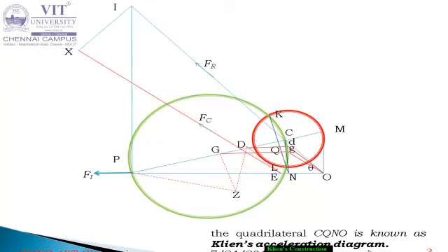Okay, so one component is over. Normal component we have taken, inertia force of the connecting rod we have taken, we have drawn the perpendicular distance Ix. For the normal force we have drawn one vertical line, but we don't know the perpendicular distance with respect to the center point. I and Fn are both acting in the same line, so there is no perpendicular distance. So Fn into the distance 0, no force will be acting through Fn. So Fn is not considered.